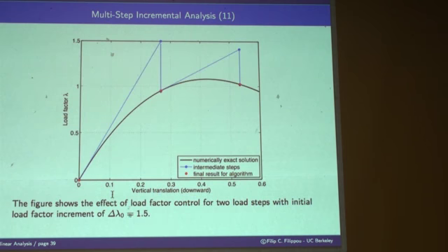You apply a huge time step, and instead of the process seeking a solution at this height, what displacement control says is, I don't insist on you applying this load. I am happy if you reduce the load and hit this point. I apply this load, I realize I can't get it, I adjust the load and end up here. So instead of insisting that the load be maintained and that the structure rises to match the load, all the load factor control does, or displacement control does, is it accepts you to reduce the load so that you can end up on this softening response.